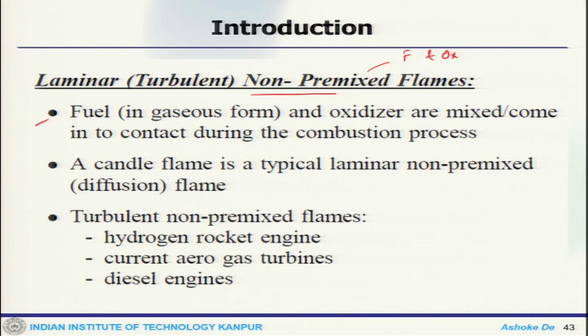Unlike premix combustion, they are not mixed and then injected to the combustion chamber. Here they are separately injected to the combustion chamber and they come in contact during the combustion process.